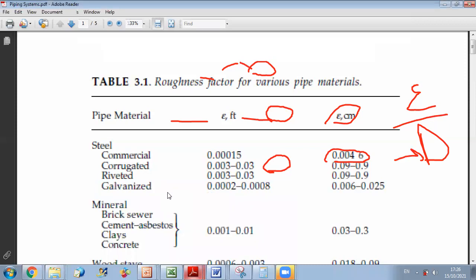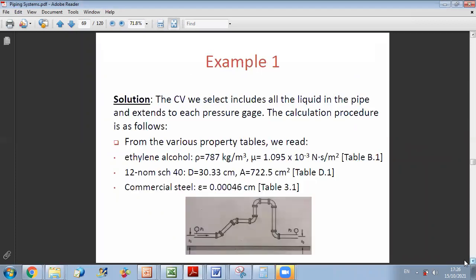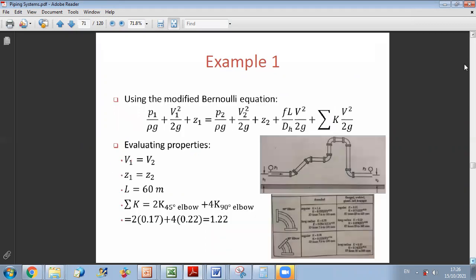Okay. So now after getting all of this information, we are ready to apply the Bernoulli equation from 1 to 2. Going from point 1 to 2, we have pressure at point 1 over gamma plus velocity at point 1 squared over 2g plus elevation z1 equals, when going from 1 to 2, we have several sources of losses.